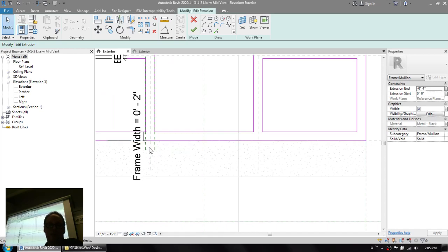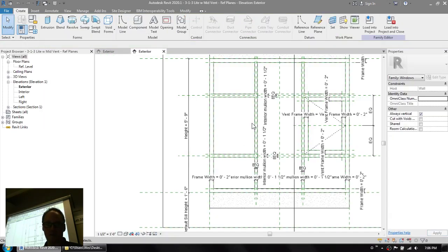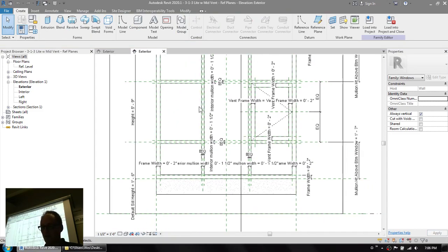It would mean then that I've got these bones, if you will, inside the extrusion, and then when I finish, see, you don't see them anymore. They're not visible. So you get the advantage of using those reference planes inside the sketch to help you constrain geometry. And of course, constraining lines in the sketch, third bullet point, to reference planes contained outside the sketch, which is this example here. So those are the three different ways that your sketch lines of extrusions in particular can be constrained.